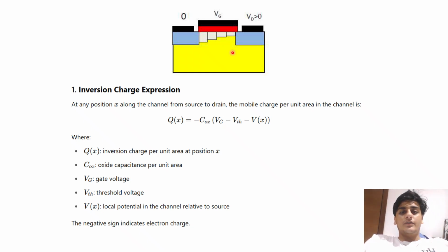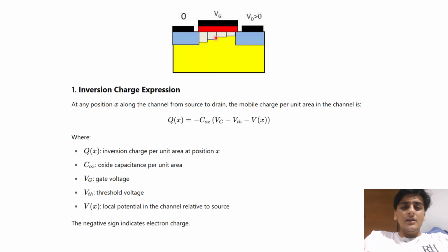The first thing, and this is your channel, your channel essentially exists here. These bars don't represent your channels. You are coming to the bars. The bars actually represent the charge density, but your channel is in the middle. This is your gate. This is where you apply the voltage to turn on and off the channel. Now, your drain, this terminal you apply a voltage. For a positive voltage that you apply, this essentially conducts electricity from right to left if the channel is formed.